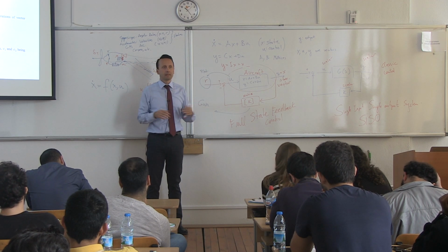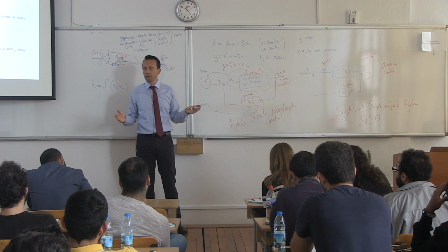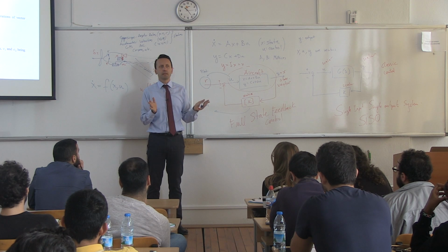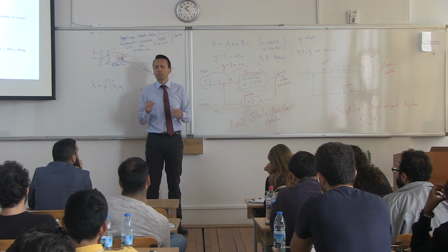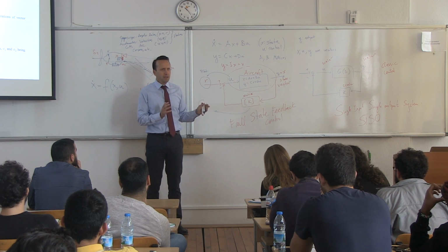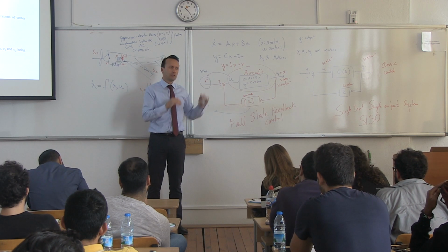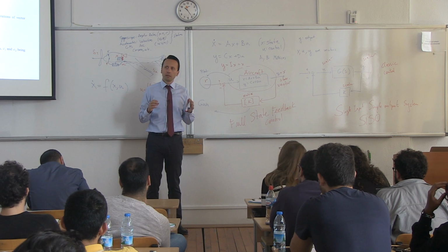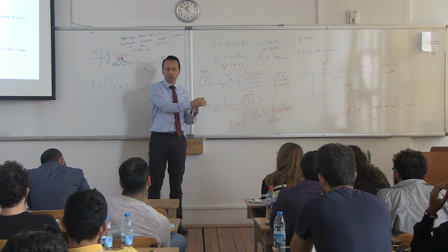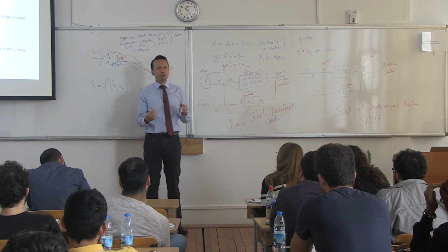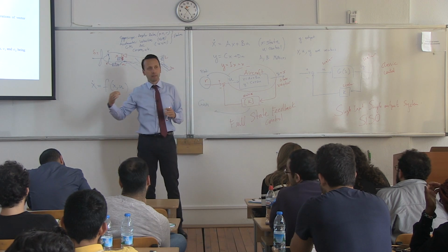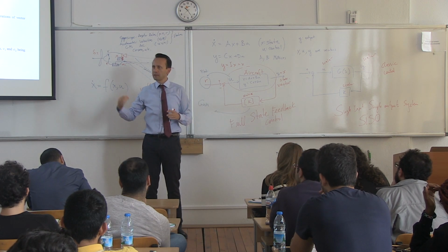For example, helicopters are quite different. When you are at low velocities, at low speeds, the equilibrium points at low speeds for a helicopter are mostly unstable. But as you go faster and faster, after 40, 50, 60 knots, the helicopter starts having equilibrium points that are rather stable. So, if you design a controller at 70 knots for a helicopter and in hover, those controllers will look quite different.